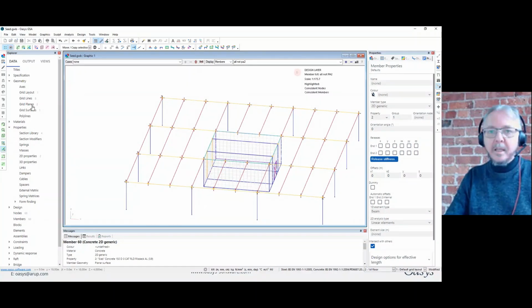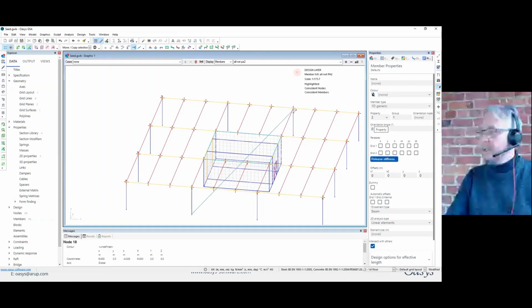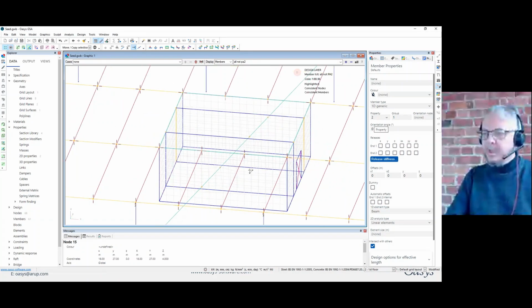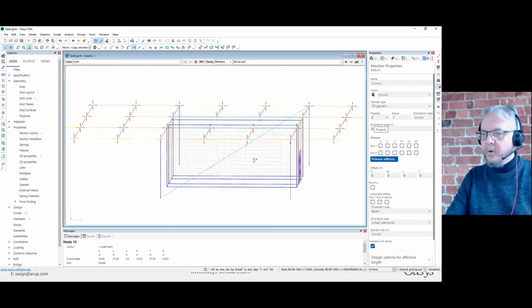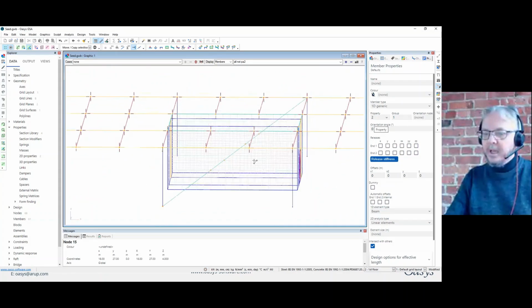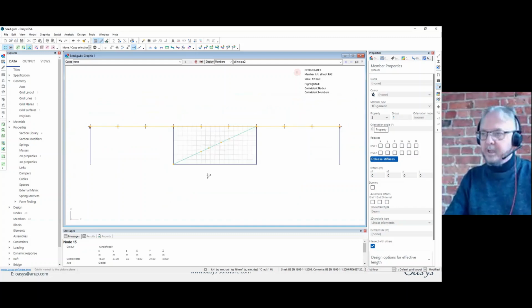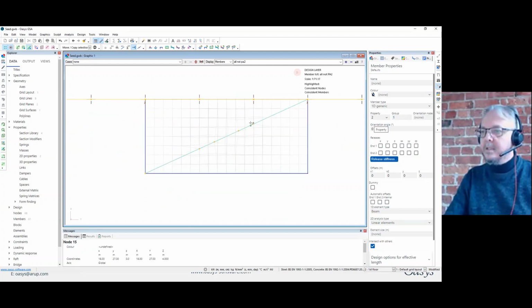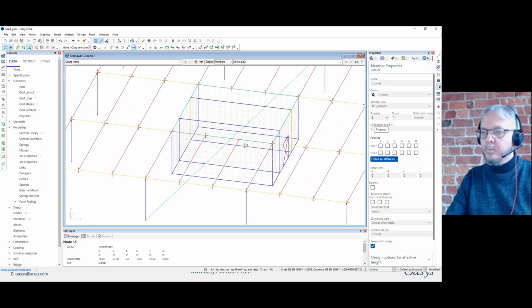And I can demonstrate this by adding in, let's say, if we were to put a beam straight through the diagonal through the core, where does that interact with the walls? Well, you see, they automatically detect each other, and you see if I look in the Y direction, you can see automatically meshing together without you having to work out where those coordinates are.